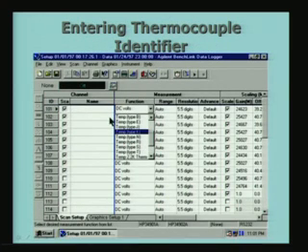In fact, what I have done is, I have also shown what other things can be done. You can see here that in this particular case, the data logger has got several types of thermocouples already built into it. I do not even have to do the calibration which I talked about. What I can do is simply tell the computer which type of thermocouple has been used, and in this case the highlighted one is temperature type K. So, if I say type K here, you do not even have to give the gain and the offset, you do not have to give it, it can actually be asked to do it by itself.